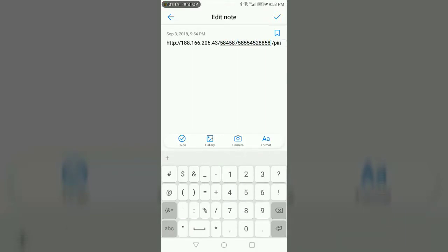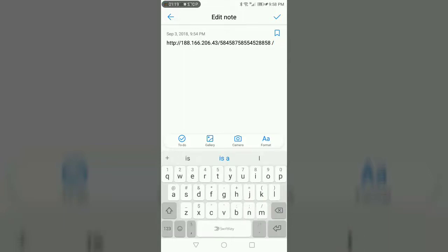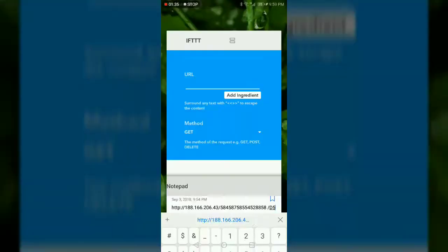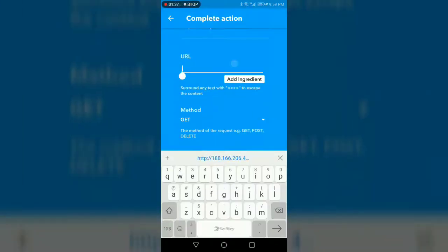Copy the auth code given by the Blynk library and paste it into the URL code, and type the pin number in the URL code. I am using D1 as the Node MCU pin, but for the Node MCU the equivalent pin in Arduino is D5, so I am giving it.